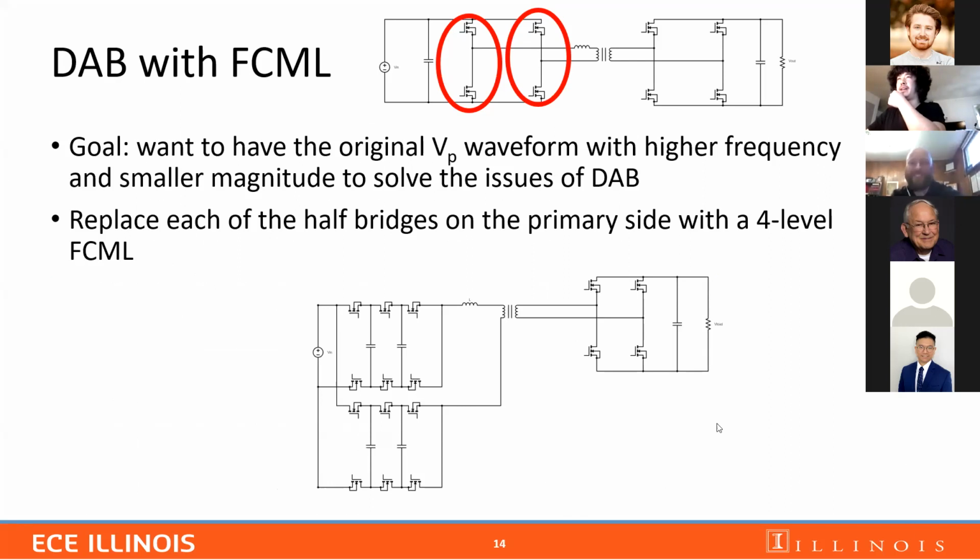So if the conversion ratio is too large, then if we use a planar transformer, we will need to use more layers in the transformer PCBs, which is harder to build. Sorry, I'm being slow here.